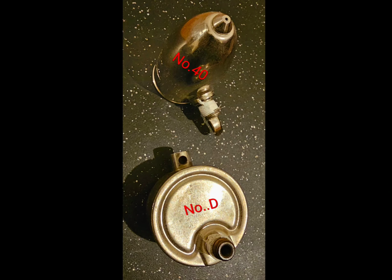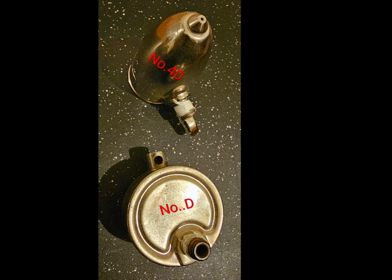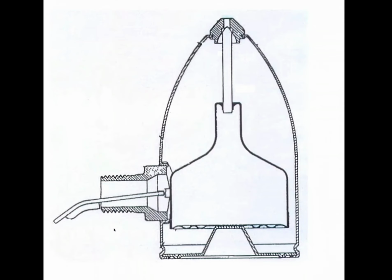As a matter of fact, there is one way you can trigger this pin to come up and cause it to falsely lock out. And that is if you turn it upside down. That's one way, or you put water inside of it, and that's another way. The water will cause the float to come right up. But those are the only two ways you're going to get that float to stay in the closed position.